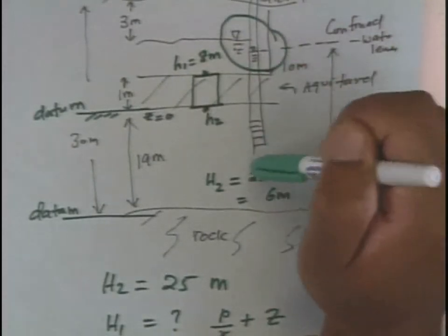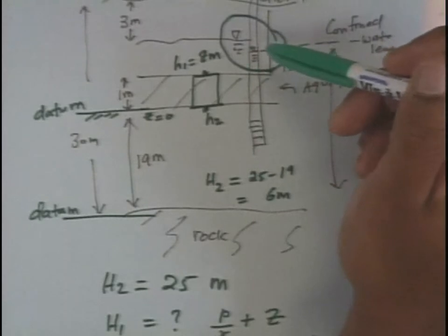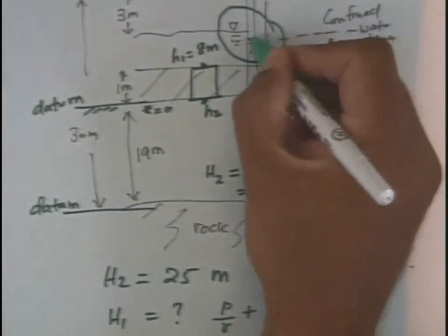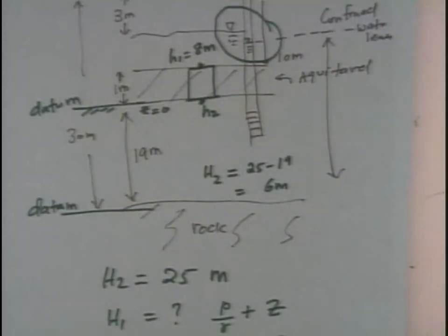If I put it in the confined, it came here. Just by looking at it, I can tell which direction it is, because that's a total head indicator, right? That's the total energy. A piezometer records the total energy, no matter what the datum is. The fact that this one records a lower total energy means the flow has to go the other way around.